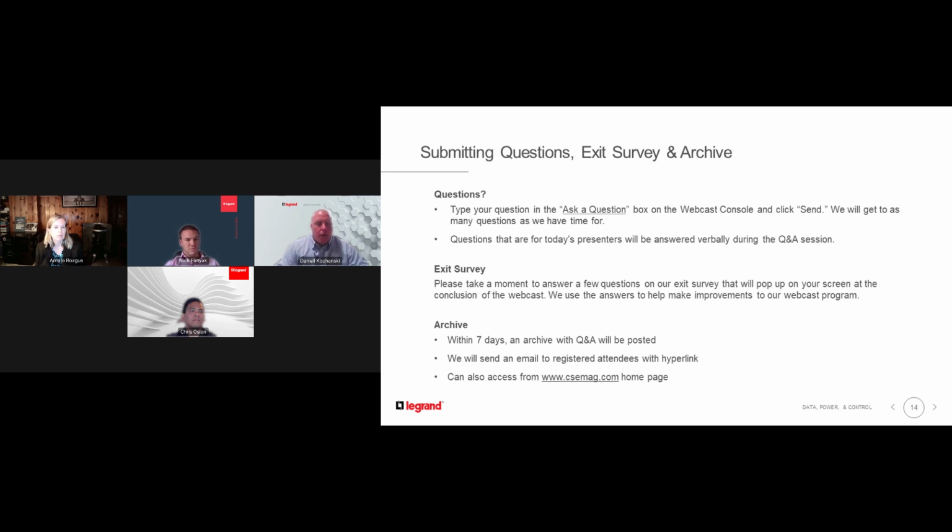Yeah, great question. Each one of our busway systems is required to be mounted on 10-foot centers, as Nick just described with the installation. The hanger method does change. It becomes larger depending upon the ampacity and the weight of the system. We have larger hangers for our 1200 amp systems that are typically hung from 1/2-inch threaded rod.